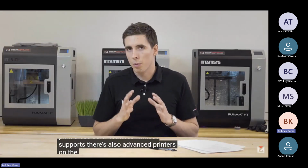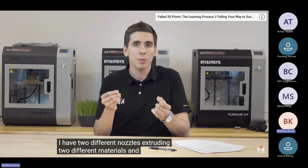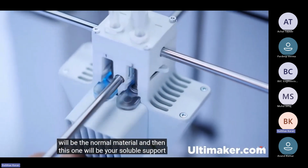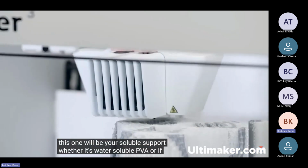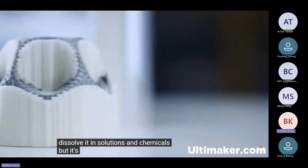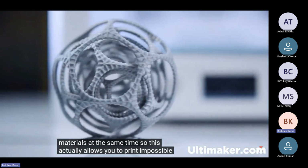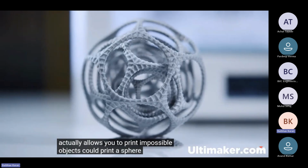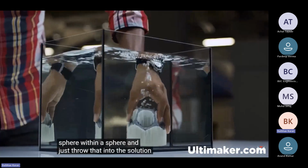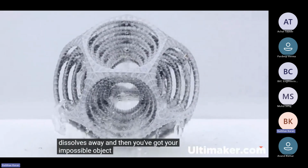There's also advanced printers on the market that use dual extrusion. So they have two different nozzles extruding two different materials. And this one will be the normal material, and then this one will be your soluble support, whether it's water-soluble PVA or if it's something like HIPS, where you dissolve it in solutions and chemicals. But it's printing two different materials at the same time. So this actually allows you to print impossible objects. You could print a sphere within a sphere within a sphere, and just throw that into the solution, let it sit for however long until it all dissolves away, and then you've got your impossible object.